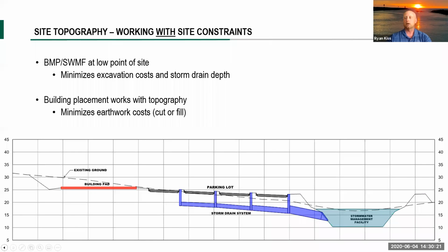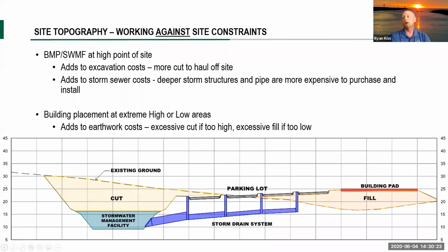Now I'm going to go back a slide. One of the things Dan mentioned as he was discussing this, oftentimes we look at the cut and the fill and we say, well, maybe we want to balance those out. So maybe this isn't so bad because we're taking the cut from this area, we're using it to fill up this portion of the site. Well, we need to be aware of the fact that that's not always possible. It all depends on the nature of the soils that we're cutting and what we need in the fill conditions. So the geotechnical report would be very important early in the game.